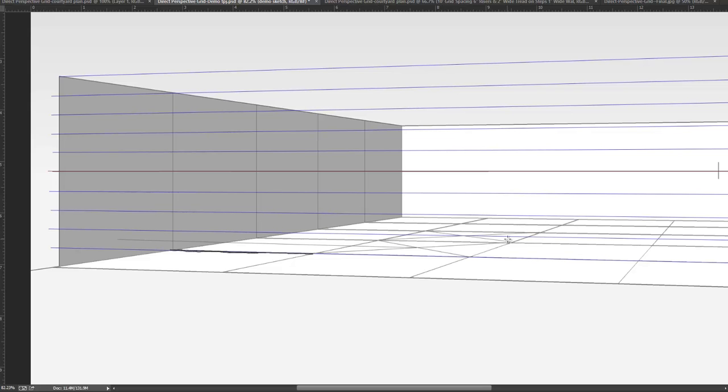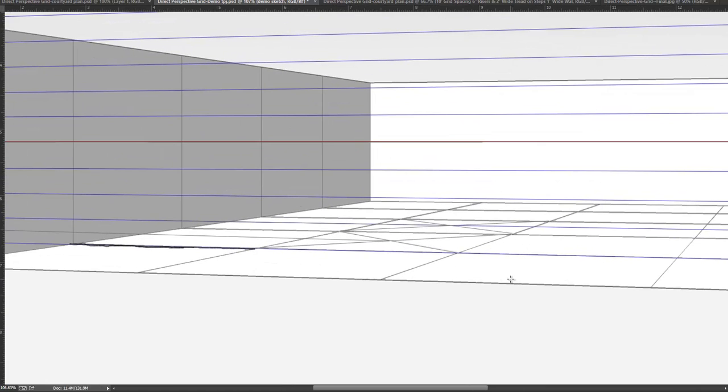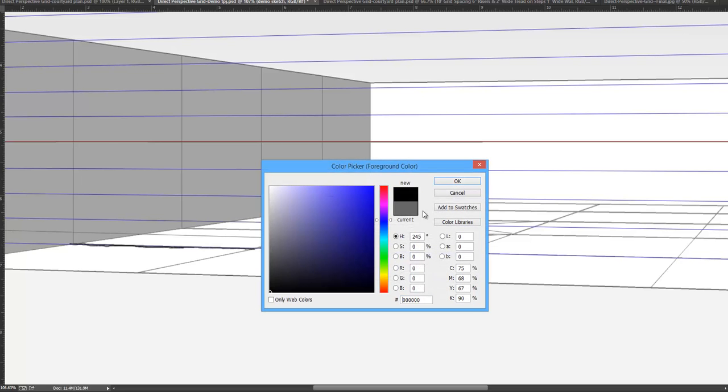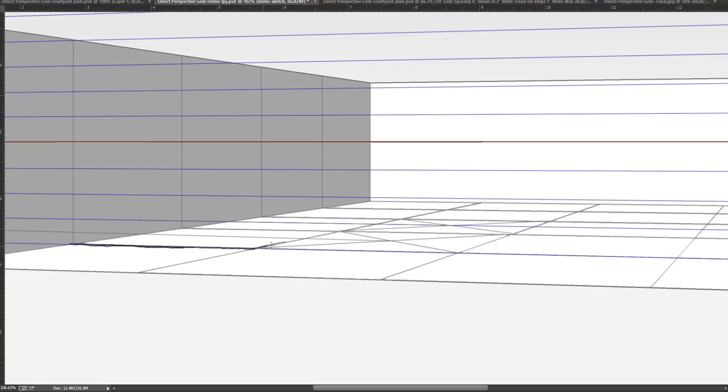And again, if you're doing this on your drawing, you'd want to make those very light lines so that it's not going to interfere with your other drawing. So use a hard lead, and do that really lightly. And since this almost hits right on that blue line, I'm going to just extend that across there. So those are kind of my working lines. So I'll zoom in a little bit more, go back to my pencil, and now I can trace down in a darker color, trace down to that 5-foot mark, and I'm going to come over.